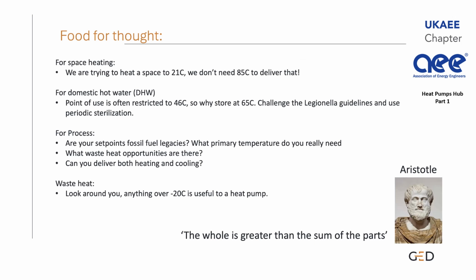For process, are your set points fossil fuel legacies? What primary temperatures do you really need? What waste heat opportunities are there? Can you deliver both heating and cooling? Waste heat, look around you. Anything over -20 is deemed as useful heat to a heat pump.